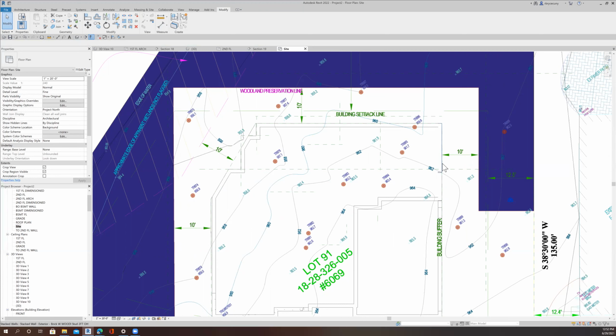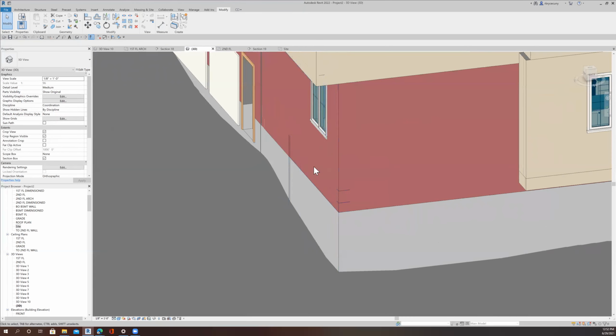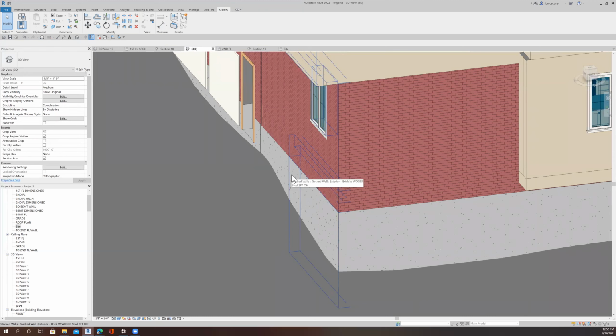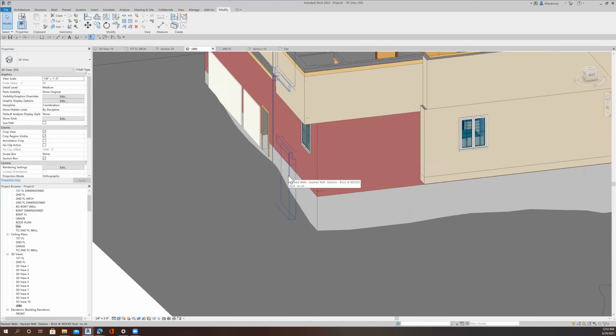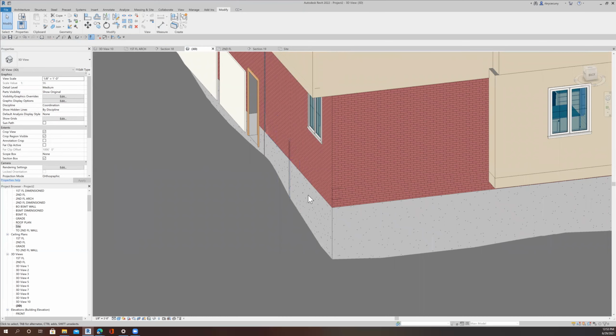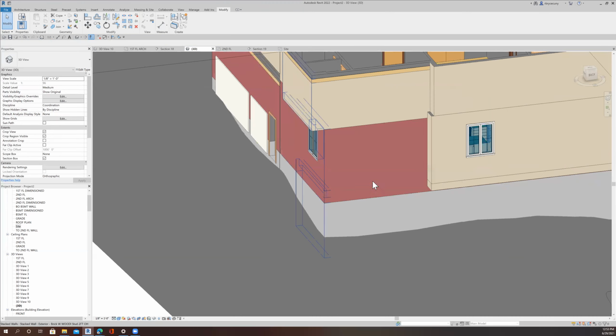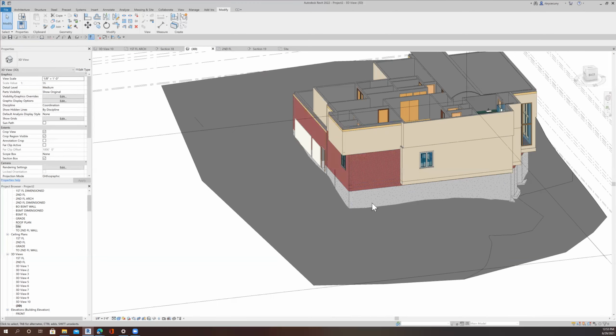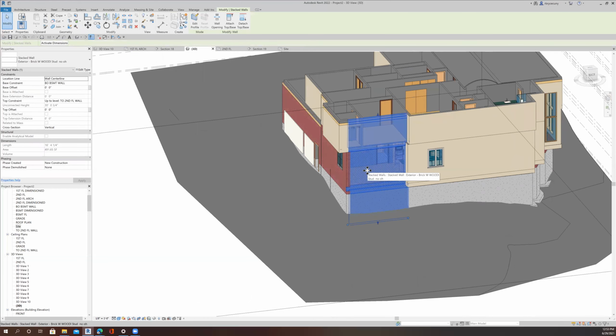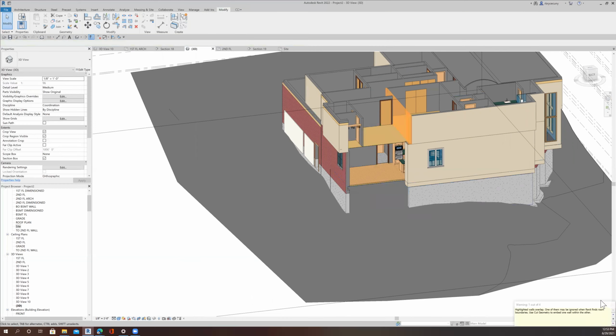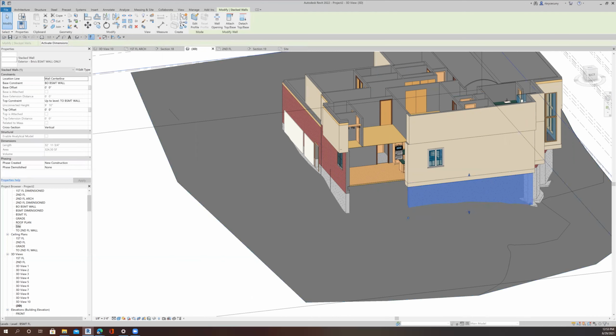And let's see, if we look at the 3D, then we cantilevered that over there a couple of feet. We might get away with it. And we might not. So let's just do this. So this wall is not good. This is a stacked wall, and I want to delete that. And then we'll say, okay, to whatever that is. Now this wall, I want it to come all the way across.